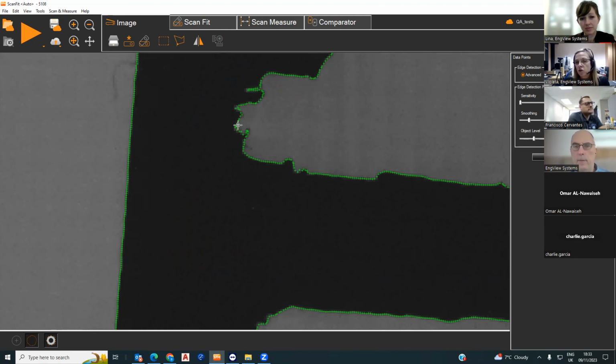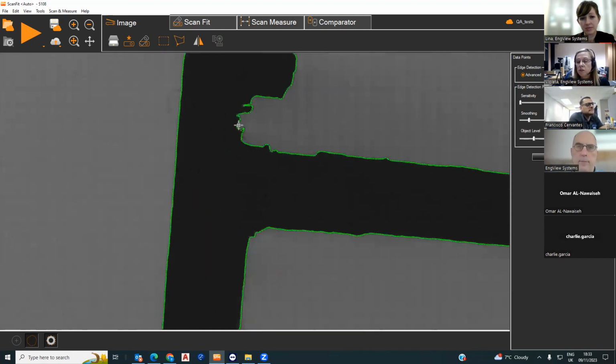If this dimension is critical for you, you need to use a manual file. I had one, but I don't see the file, but no matter, I'm sure that you have manual files. You need to remove these burrs and turnings and measure the profile.